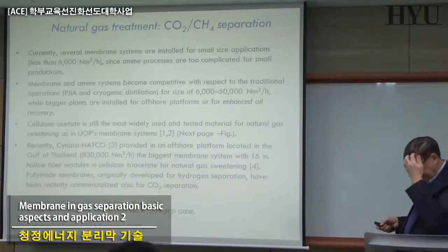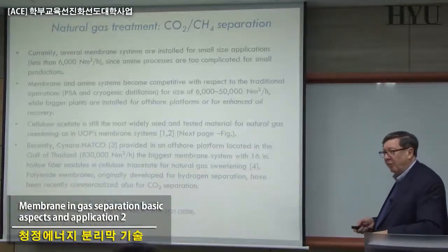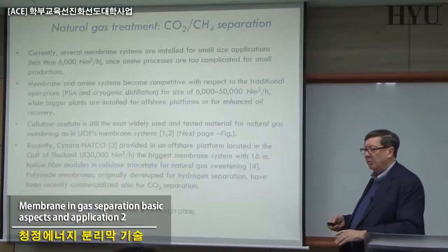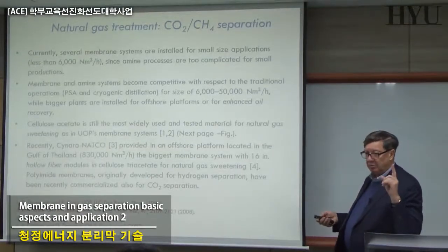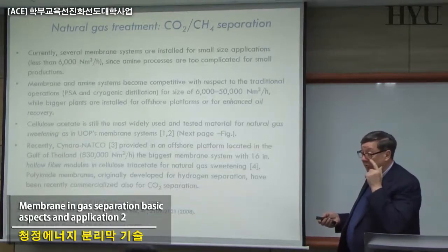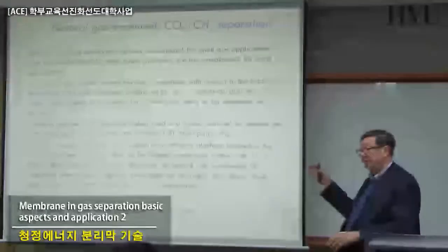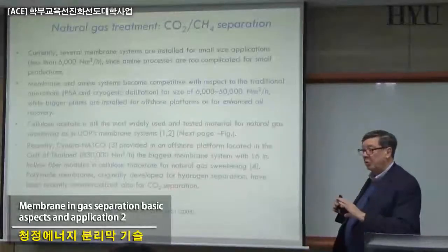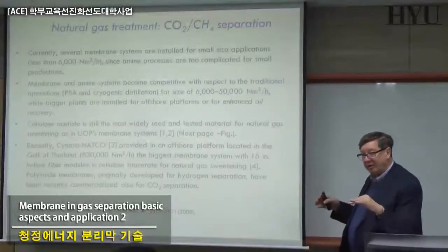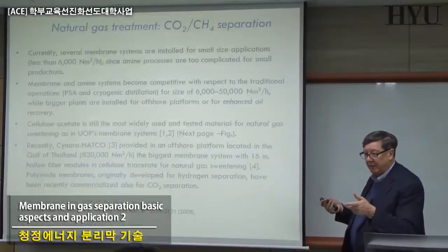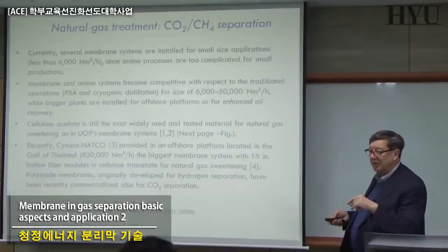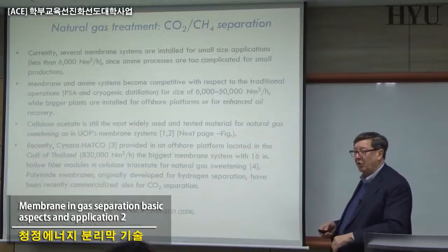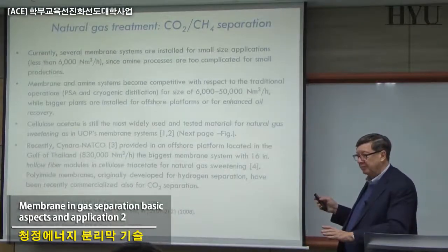Remember that it's interesting that one of the most utilized membranes still today is cellulose acetate. The same membranes that people were using for making reverse osmosis. Cellulose acetate is perfect, except one problem. The problem of cellulose acetate, you know, when you have cellulose acetate for desalination, still today, these membranes have to be always wet. If they dry, they become fragile. And so you cannot use cellulose acetate without accurate control of the situation. Always wet.